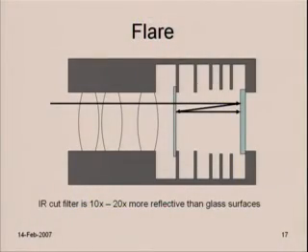So the problem, what ends up happening is that you can't get an infrared cut filter, what's called the dichroic infrared cut filter, that's the stacks of materials coated on, you can't get one that has anything like 1% or less reflection in the visible band. What you can get is maybe 2% or more likely 4%, and that's fairly reflective. And so you combine this with the sensor at the back, and you have this really great path for sending light in and then sending another image of it back onto the sensor.